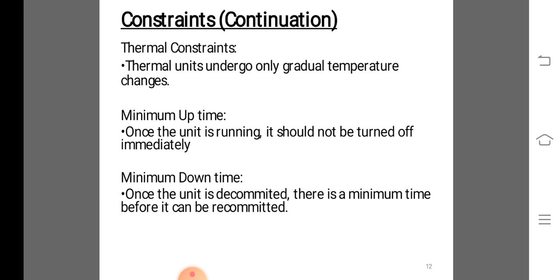This allows the automatic generation control system to restore frequency and interchange quickly. In the event of a generating unit outage beyond spinning reserve, the unit commitment problem may involve various classes of scheduled reserve or offline reserve.